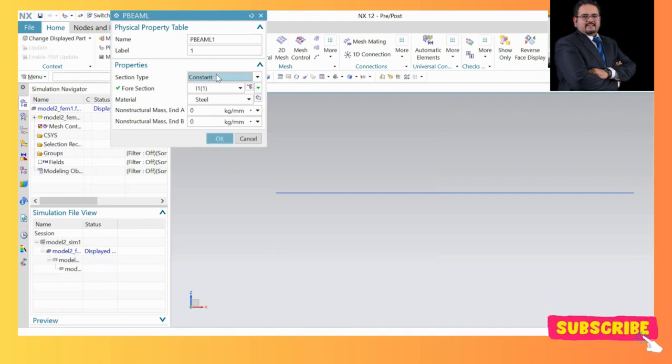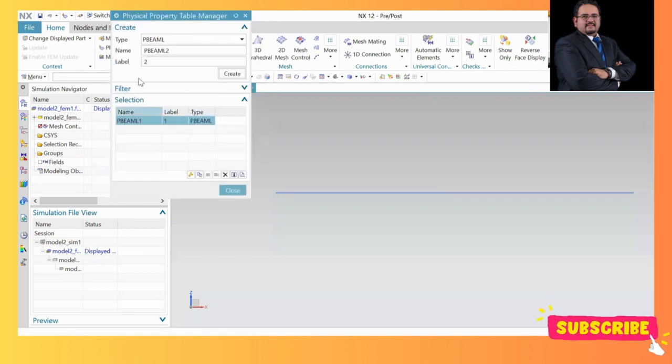And I can press OK. This is a constant profile cross section, but it can be tapered if you want. Press OK to this one. And after this one, say close.